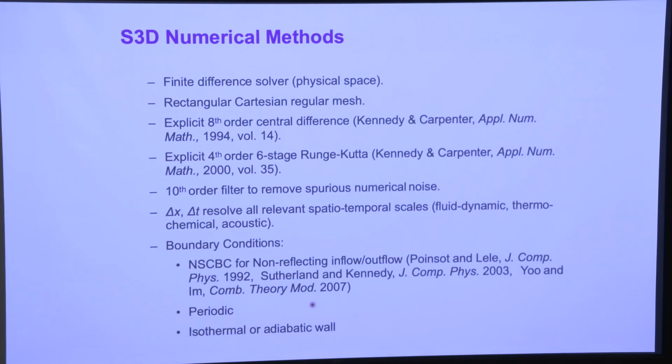And I've already discussed the selection of the spatial and temporal resolutions that is required in order to faithfully resolve all of the relevant spatial temporal scales for the flow, the thermochemical flames and ignition, and also for acoustic time scales. So we resolve all of those scales in this compressible reacting flow.